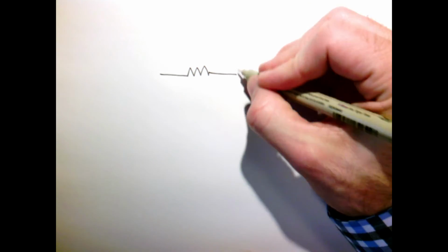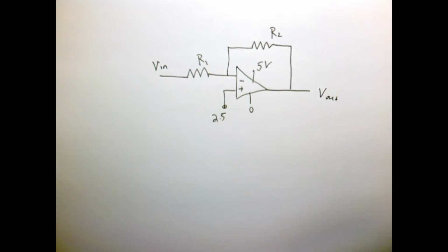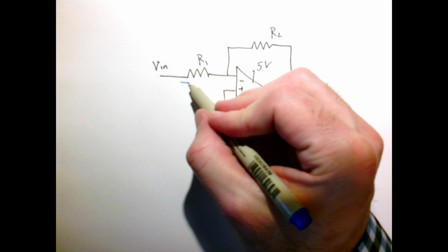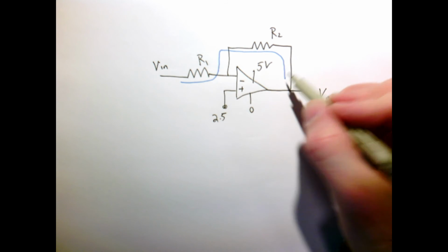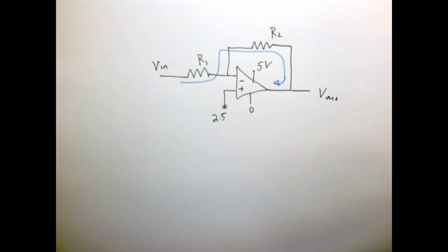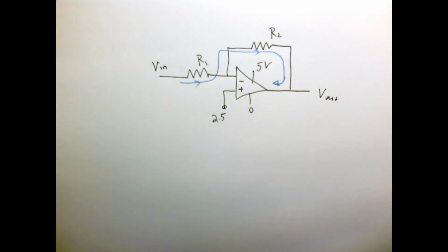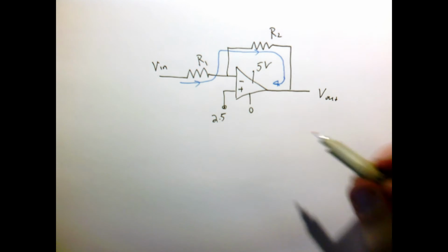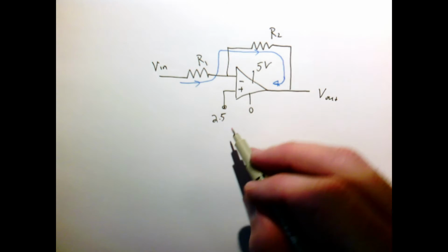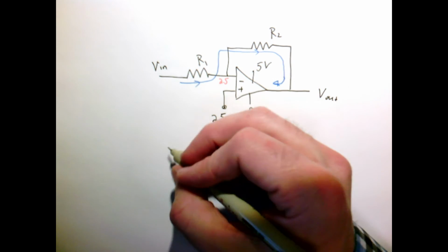One simple modification of this circuit is just as in the previous one. We can do exactly the same thing, except we connect this point here, V plus, to 2.5 volts. But the analysis is exactly the same. There's only this current flowing through here. And if this is connected to nothing, then the current would be going into the op amp. So the current flows through this resistor, through that resistor, and into the op amp. By our second rule, if this thing is anywhere between 0 and 5 volts, the voltage there better be 2.5. And so therefore we can analyze the circuit in the same way.